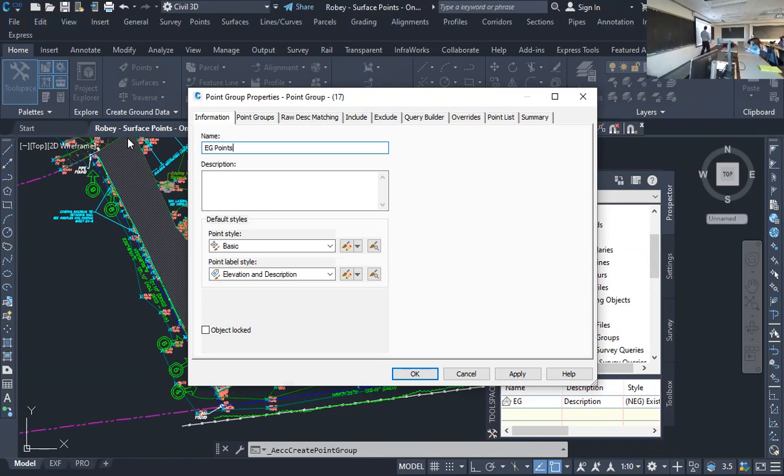contours. Same thing with your hub, right? Your hub might stick out of the ground 3-4 inches. Should you include that hub in the surface model? Not if it sticks up out of the ground 3-4 inches, because it's going to pull the contours up at that spot.